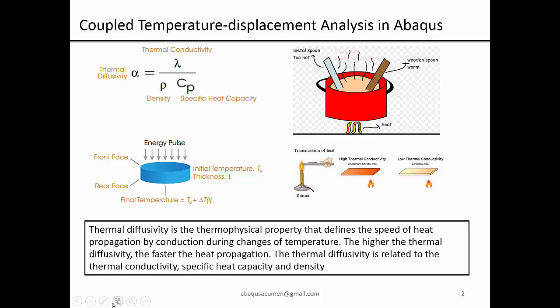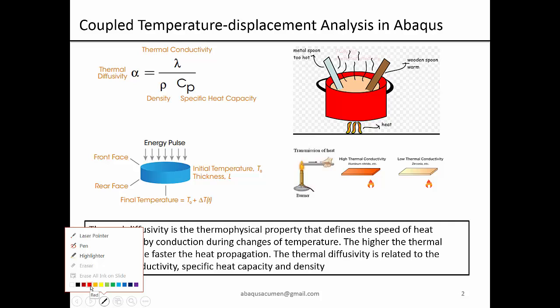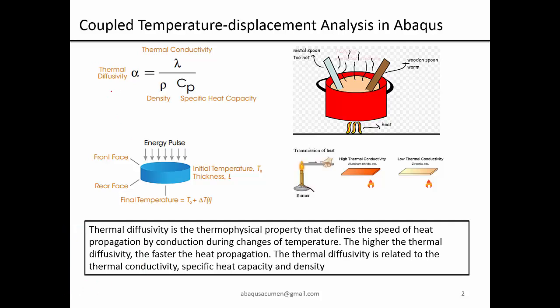So let's understand the first, thermal diffusivity. Thermal diffusivity is also called the thermal robustness of the part. If your part should be very thermally robust, so that very high thermal stresses are not generated, then it should transfer heat immediately. If you have high conductivity, low density and low specific heat, then people say you have high thermal diffusivity. If you have high thermal diffusivity, the thermal stresses generated are quite lower, and thermal diffusivity is high in metals.